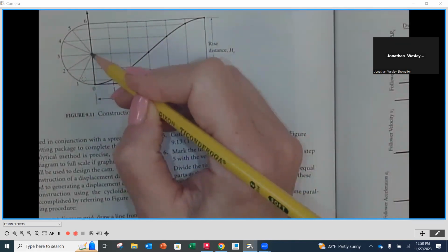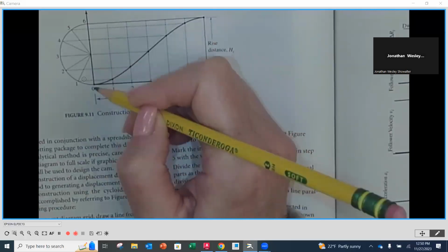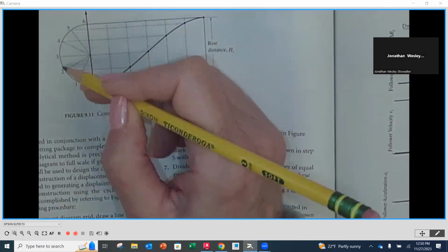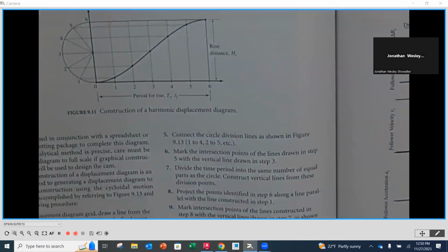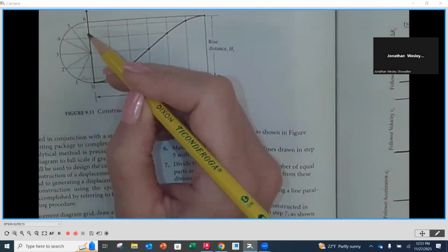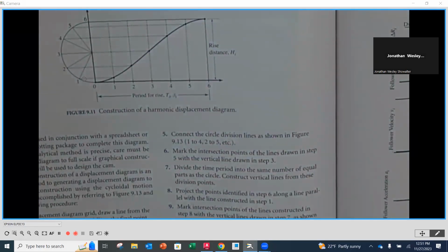So that means that at the 1 inch mark, as we look at this as 2 total inches, that's going to be the center of the radius that we create. And that radius is going to be a 1 inch radius, or a 2 inch diameter arc here on one side. Then you're going to notice that we are going to be breaking this into 6 equal segments. So if we've got 180 degrees here and we want to break it into 6 equal segments, how many degrees would we need to rotate each one of those line segments?